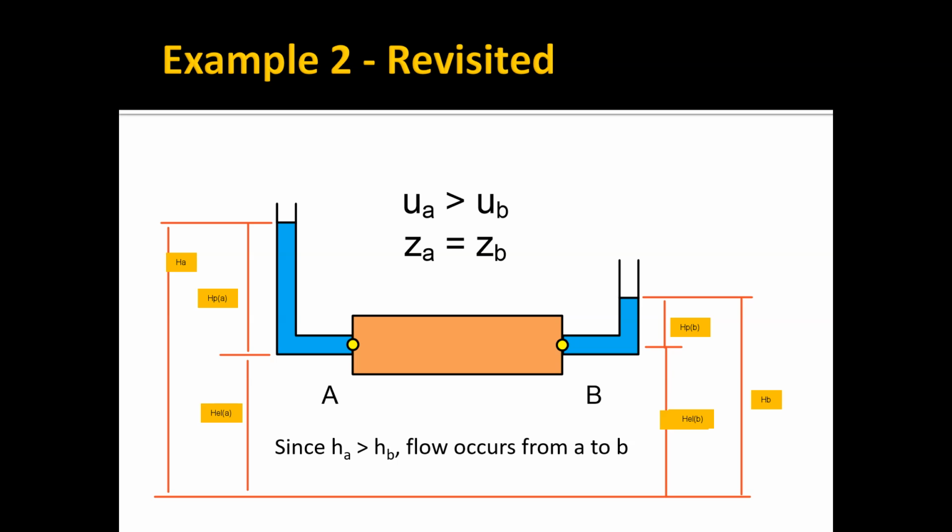So where there's the steepest drop off of total head or water table elevation, that's where the groundwater is going to flow. The whole point in groundwater modeling is to come up with an estimate of how the total head is distributed throughout an aquifer system, because once we know that, we know how fast the water is going to flow, we know what quantity of water is going to flow, but it all comes back to this principle of hydraulic head. So now in our class we'll do some exercises associated with this, and then next time we'll build on this and come up with something called Darcy's Law.